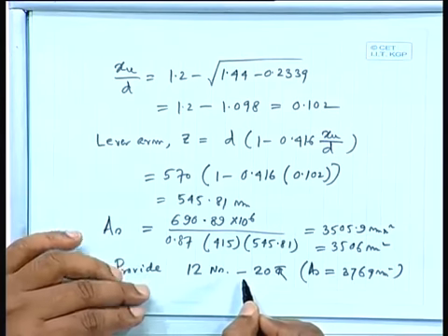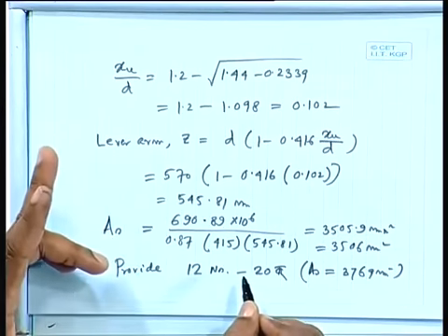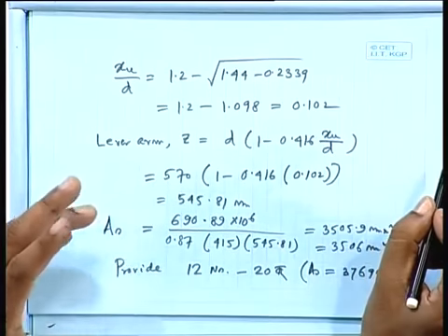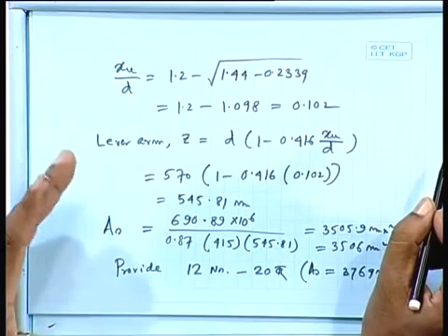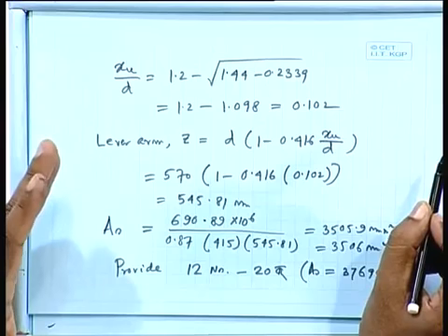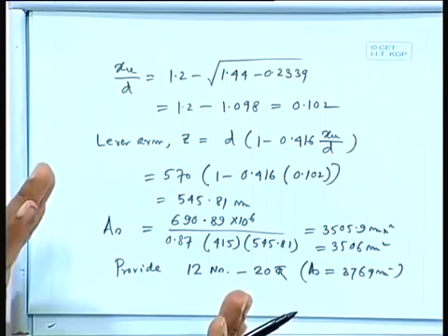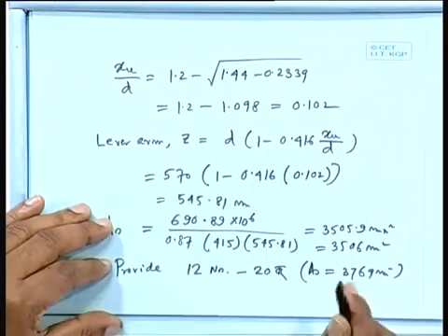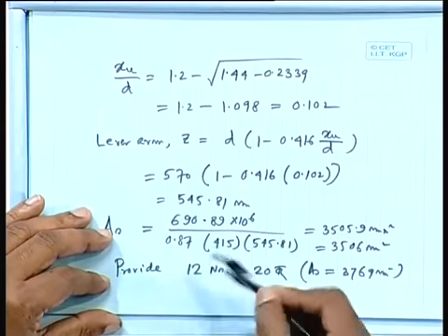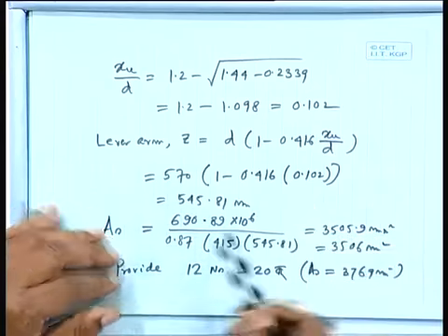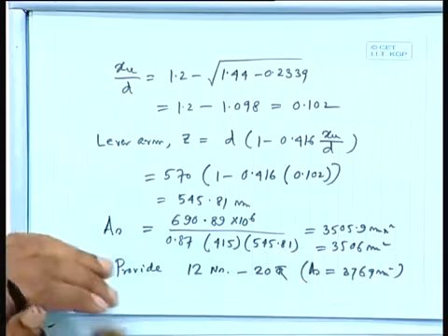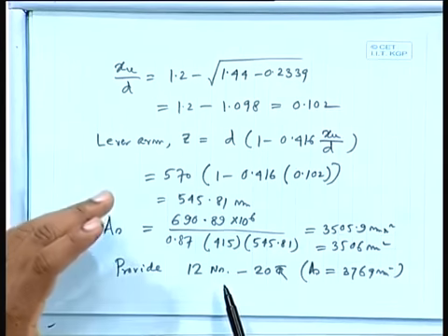You can mention like that, but instead of taking the whole length, I have always considered the length equal to 3 meter. One way you can do it, the same thing, you could compute the bending moment or shear force for say 1 meter length. In that case, we have to provide 20 mm bars at the rate of certain spacing. Whenever we are talking about 1 meter, but here we have taken the full length, and that's why I am specifically specifying the numbers.